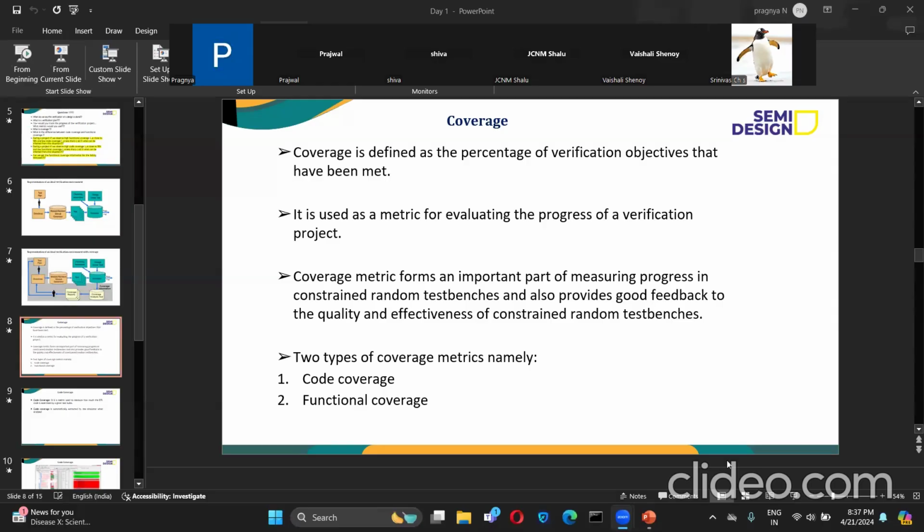What is this regression? Who was the one asking the question? Shiva, right? We'll have a tool where we can add all the test cases at once and launch a regression where we can put some count. For example, for each test case we can put a count of 10. Then 10 times with different random seeds it will run the test case and give us an entire report of how many test cases are passing and how many are failing.